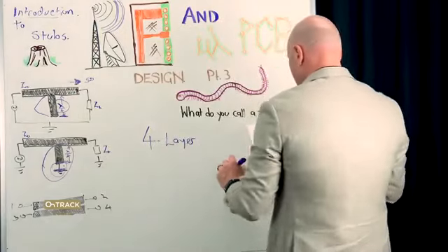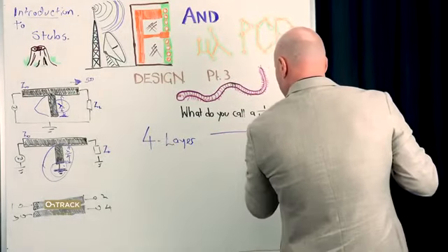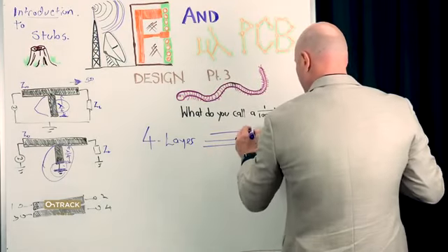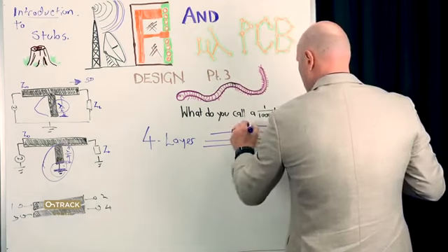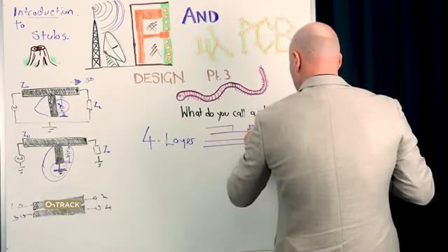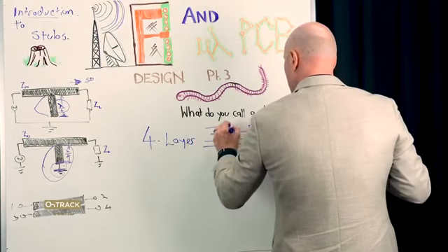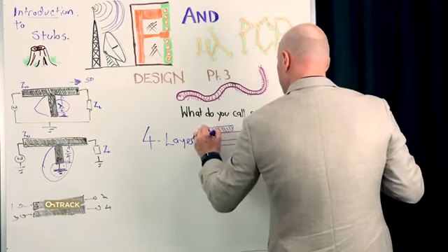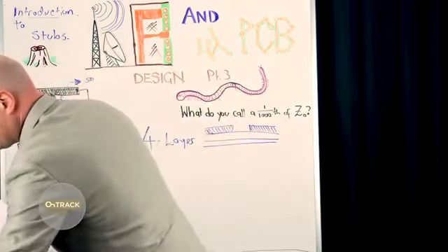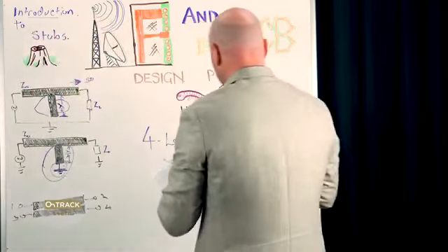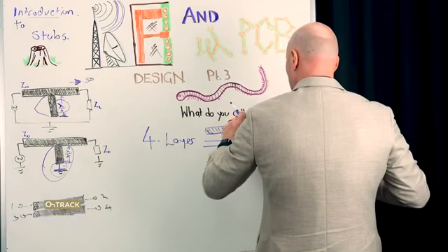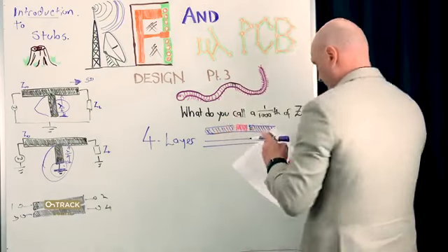4-layer, and this is what it's going to look like. I'm going to open the solder mask over my traces. Now they use ENIG, which does affect the performance a little bit, but just for example's sake I'm going to keep it simple. So there's my copper trace with the purple solder mask around it.